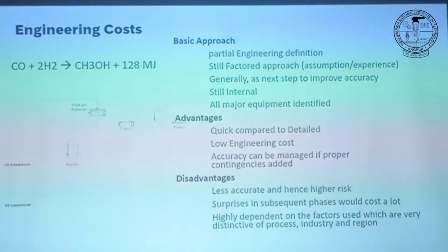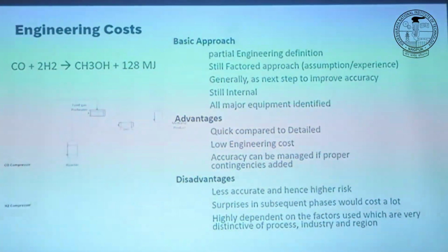So what I will do, instead of one pump, I will install two pumps. With this, my production outage because of a failing pump I eliminated by installing another pump, like a spare pump. There you have to weigh it against the capex, because with every additional piece of equipment you are increasing your cost. So you have to make this analysis.